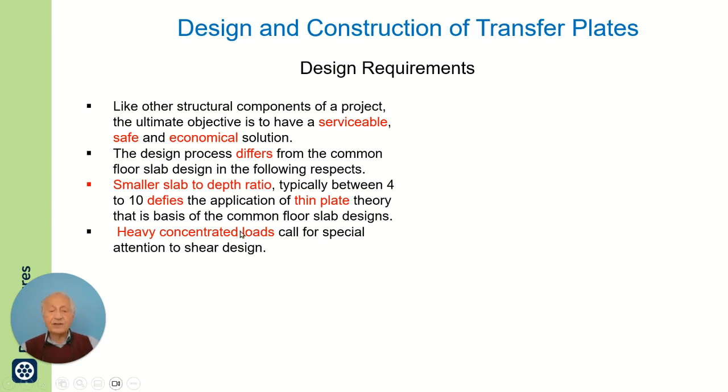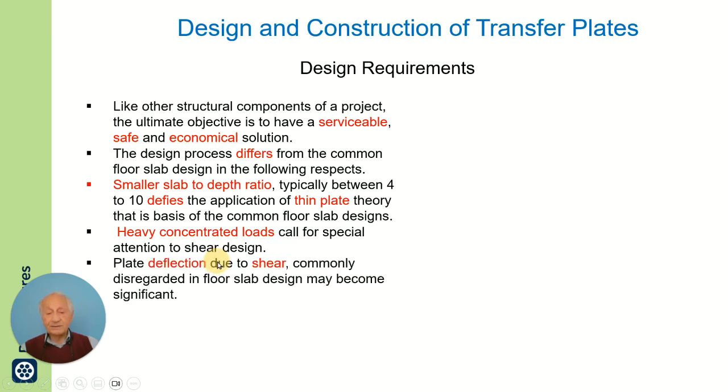Heavy concentrated loads call for special attention to shear design. Plate deflection due to shear, which is commonly disregarded in floor slab design, may become significant. It is very rare that in a residential or commercial building you consider the shear deflection effect of the floor. Not here. Here it could be significant.